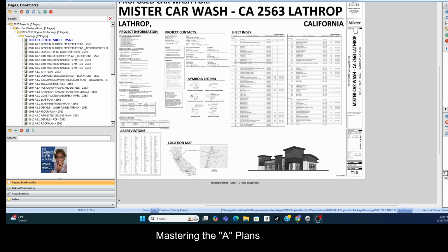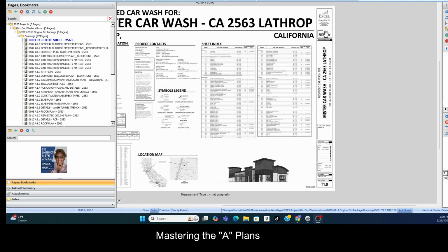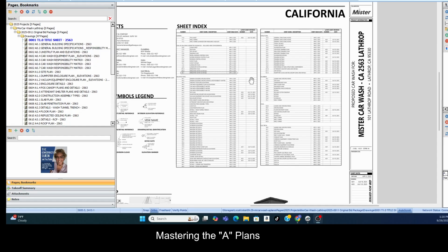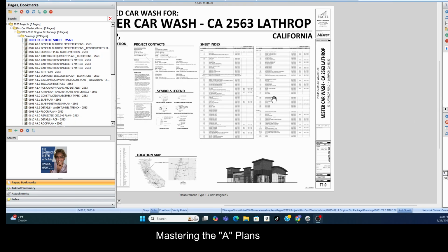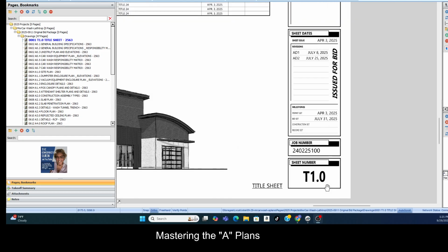And there are a couple things that are standard to all of the sheets, but we see it here in the title sheet where the right band is oriented a little different. And it used to be back in the day they'd have, or even today, the full set of plans and they'd roll them up. And so they wouldn't want to open up just to get to the electrical or mechanical set. They didn't want to have to look through every sheet. So when you roll it up, all you have to do is look at this portion, which is the page, the title sheet. We know it's the title sheet, and it's the sheet number. And so we could just flip it that way, pull out the sheet we need, and not have to disturb all of the other sheets. Okay, a couple of things we're looking at here.